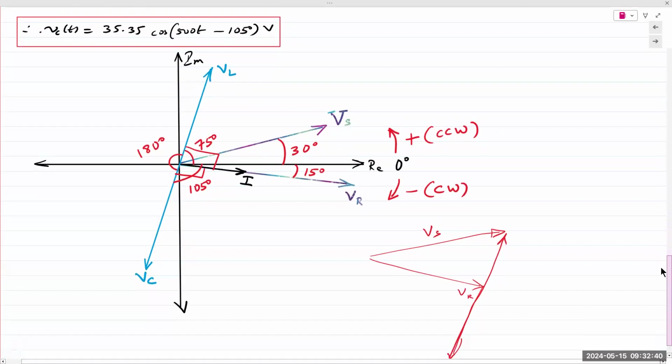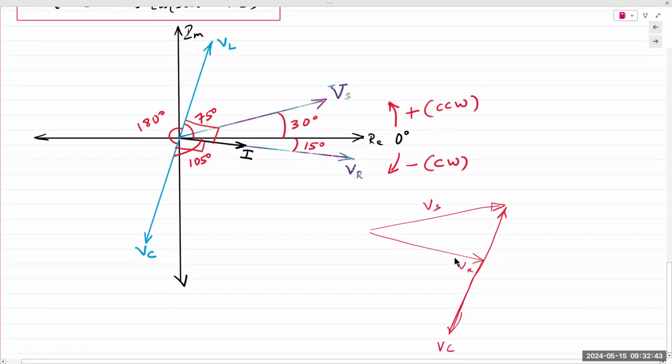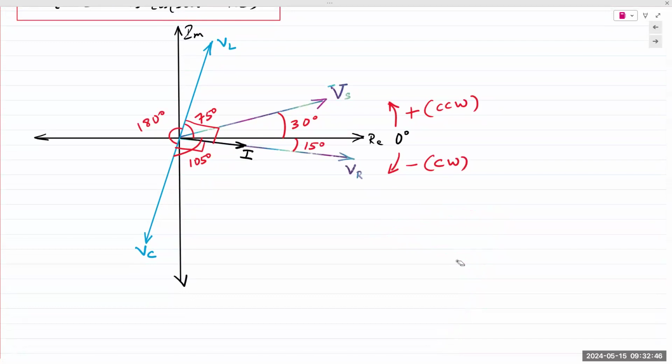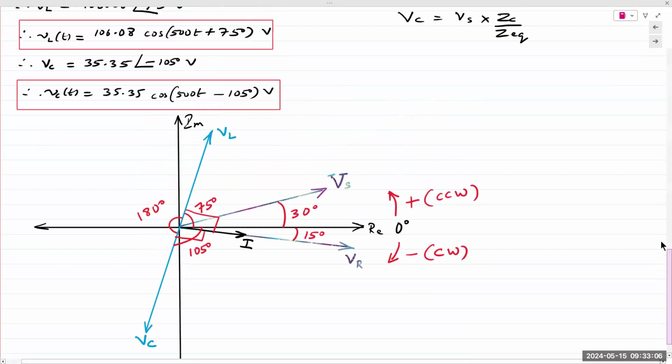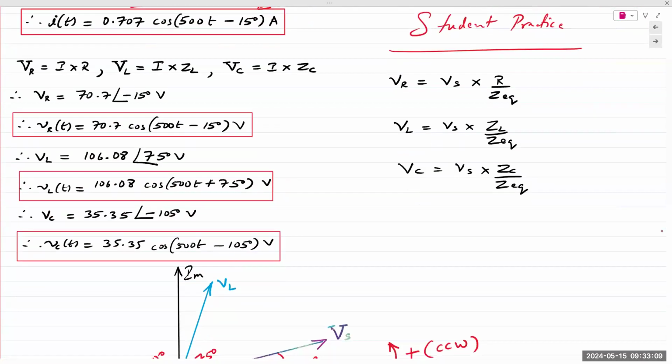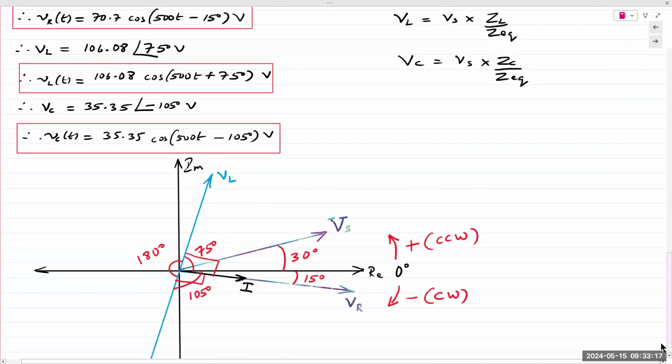And finally, the phasor diagram. Okay. So phasor diagrams can be used to plot multiple different voltages and currents. Here, what we are doing is we are plotting all the voltages with respect to each other. And because the current is the same, we only plot one current. Okay. The way to plot a phasor diagram, again, and I talked about this, you only need 2 things, right? It's a vector. So you only need the angle, you only need the length. And these are, of course, not to scale. You simply take the angle.